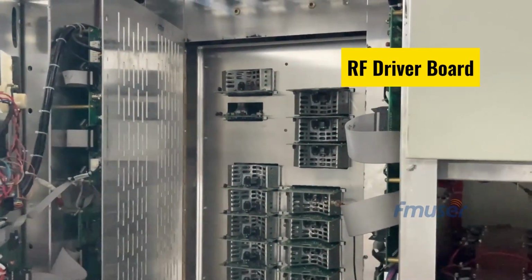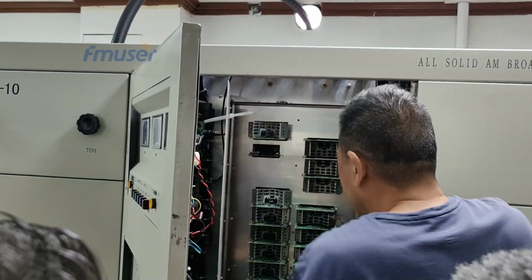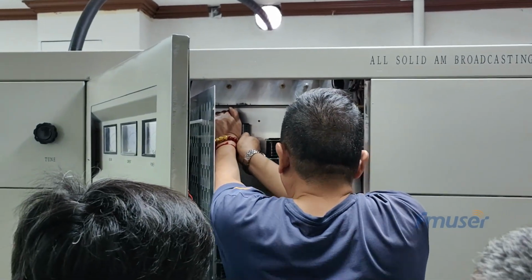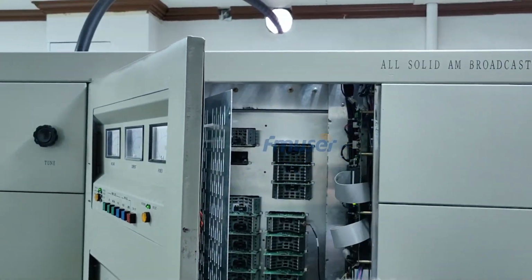Driver troubleshooting. The RF driver module is a crucial component in a 10 kW AM transmitter that plays a significant role in amplifying and controlling the radio frequency signal before it reaches the power amplifier stage. If the driver RF board becomes loose or is pulled out, the monitoring panel's driver indicator light will turn red as an indication that the RF driver module is not functioning properly. This serves as a visual reminder to the operator to check for any loose connection or issues with the board. The RF driver module's importance lies in its role in signal amplification, control, and preservation of the signal quality.